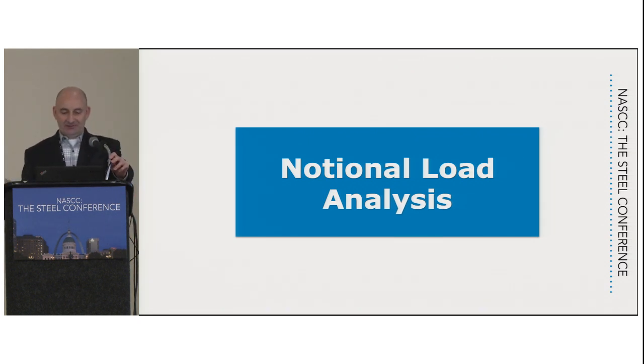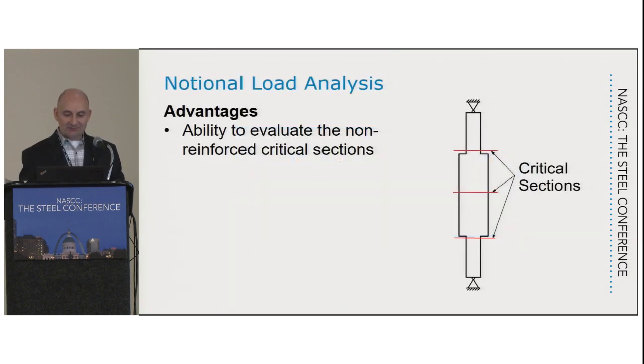All right, my favorite part of this, actually the strangest part of the presentation, is the notional load analysis. But let's go over some advantages of using notional loads, and then I'll show you what we're talking about. I think everybody knows what the notional load analysis is from the direct analysis method. It's been in the spec long enough. And the reason I call this notional load analysis instead of direct analysis method is because there are some differences that we'll talk about. For one, we're talking about pin columns right now.